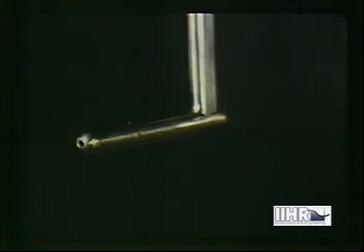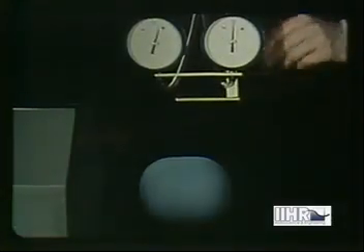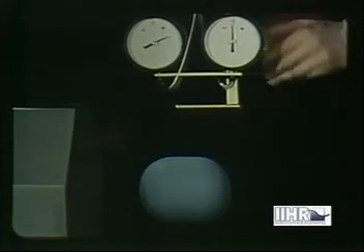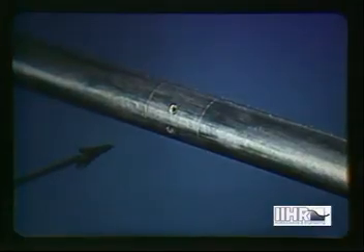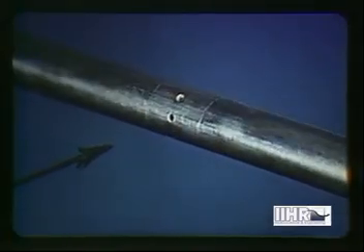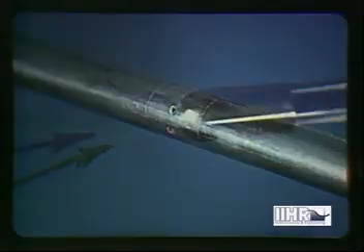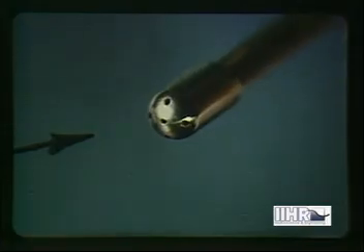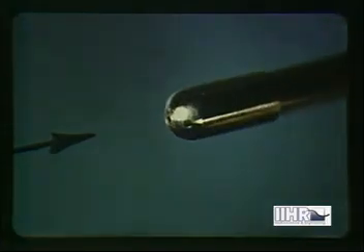Such a pitot tube is here being used to indicate the velocity distribution alongside a body of revolution. Note the different indications of velocity change as the tube leaves the boundary of the body and as it reaches the edge of the stream. Velocity tubes can also have many other forms, such as this two-hole magnitude and direction indicator for two-dimensional flow, or this five-hole instrument for determining the velocity, magnitude, and direction in general three-dimensional flow.